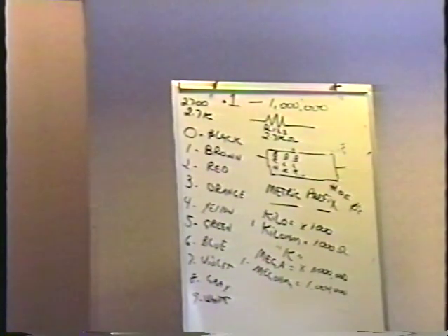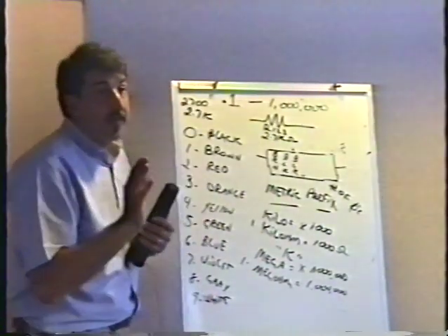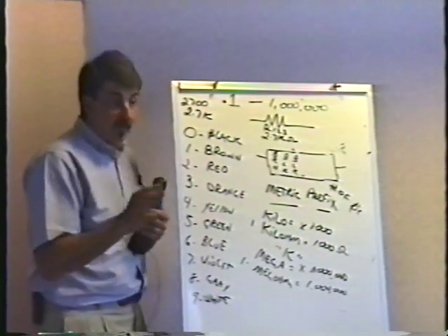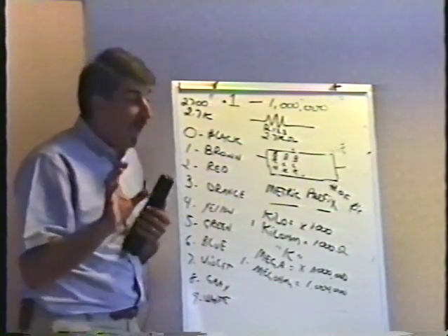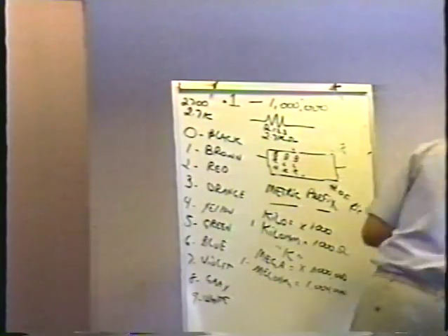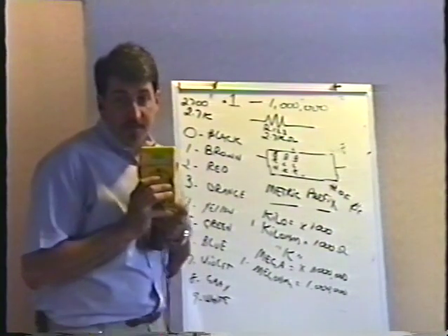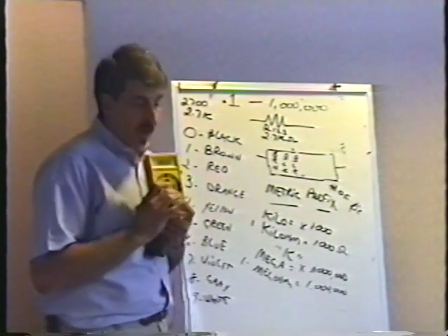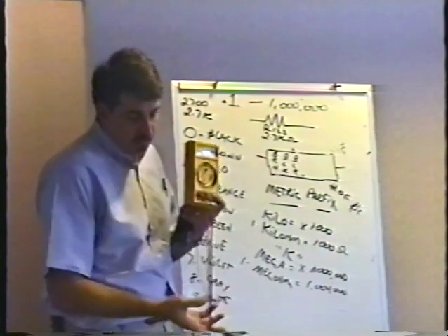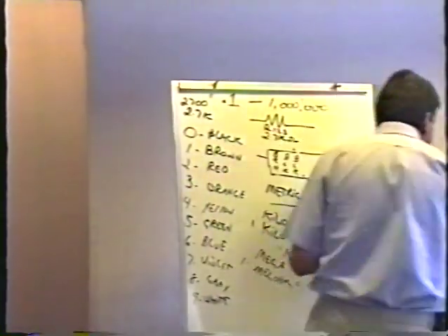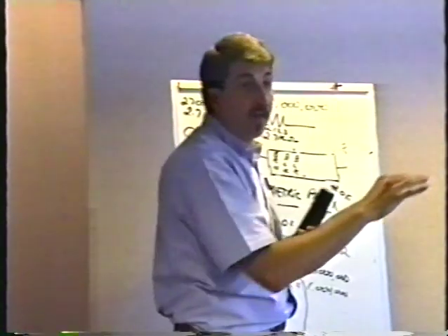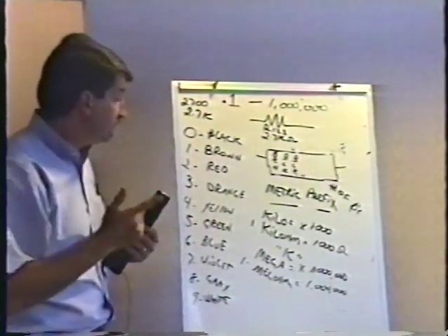As we'll see in just a little bit, when you start doing this resistor lab, the proper setting for your meter, if you don't have an auto-ranging meter, is as low as you possibly can without getting some kind of an overload indication. Now this particular meter says OL on it. That's when the resistance is higher than what you have it set for down here. Other meters might just have the number 1 with no digits after it. You'll see when we start doing the resistor lab how simple it is, and we'll do that in just a few minutes.